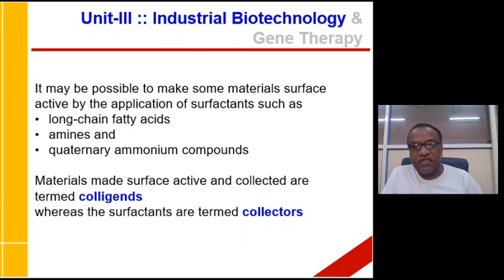Right. So, it may be possible to make some materials surface active, because foam flotation makes use of the surface active property of materials. So, you can make some materials surface active by applying surfactants, and these surfactants could be long chain fatty acids, amines and quaternary ammonium compounds.